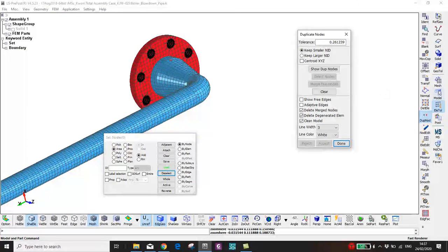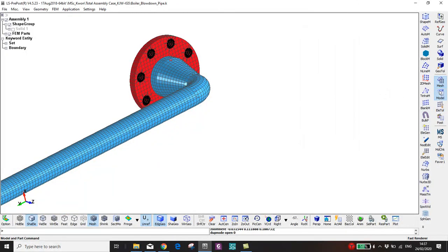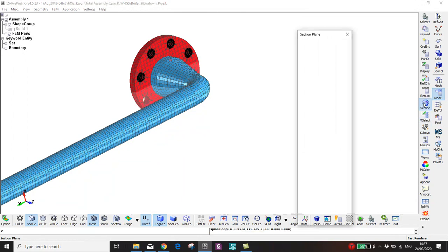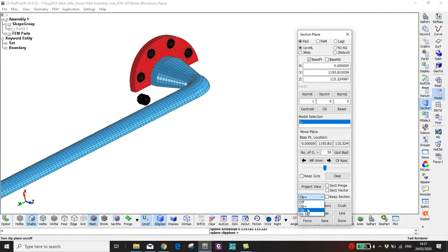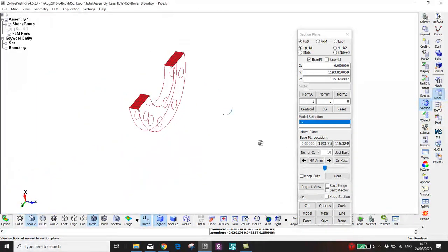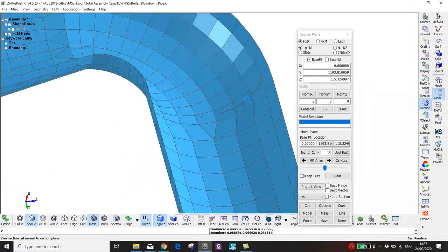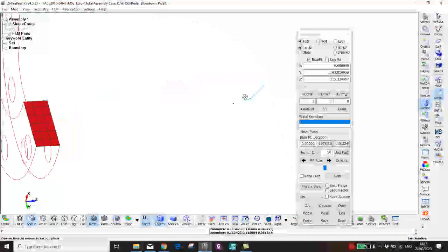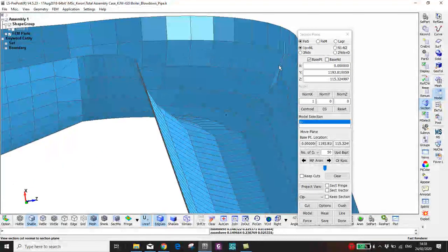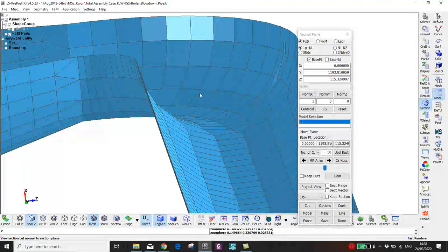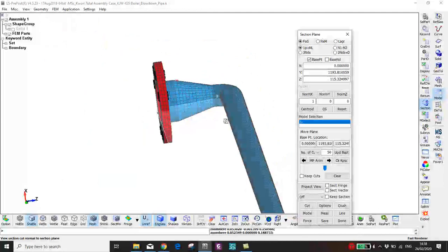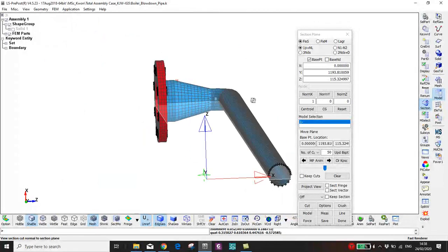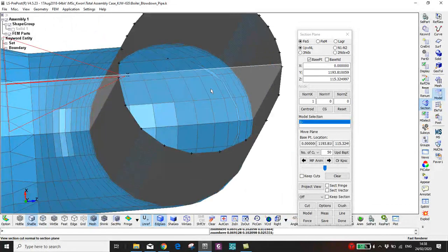Okay, I go back again to the section view, model, section view, click on negative. Just want to make sure. Okay, you can see here, this is actually the remainder from the previous inside circle, so I need to delete that, because we already defined the thickness, so we don't need this.